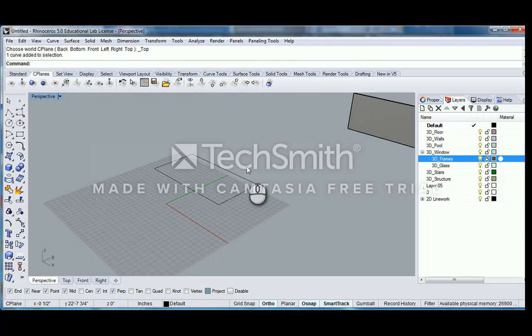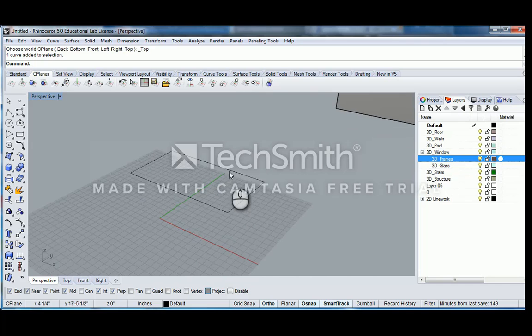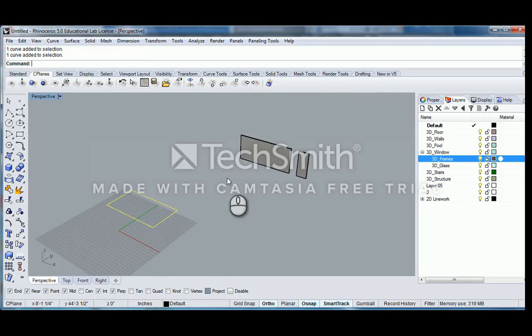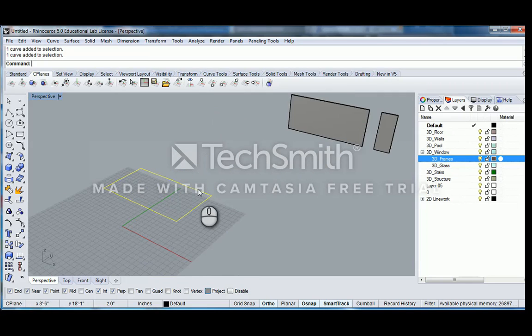This starts to get more involved when you're doing some kind of higher level surface analysis. But the directionality of the surface actually is very important to orienting objects on that surface, flowing objects along that surface. Certain Grasshopper commands rely on, or demand in fact, knowing the orientation of the surface, or else the command won't work. Within any object that we see in a scene here, there is embedded information that is not immediately visible, and that's important to that surface.